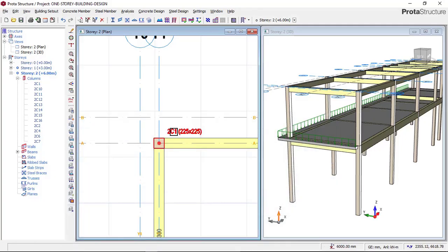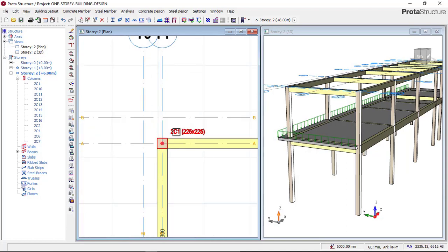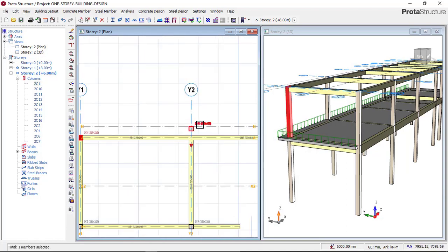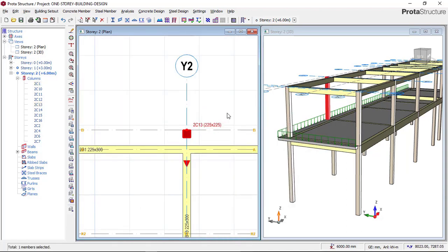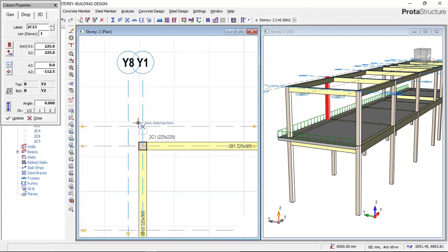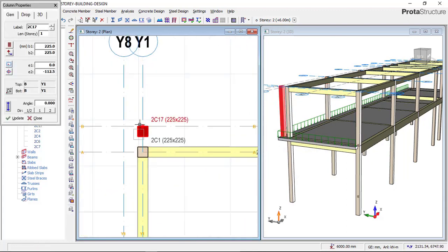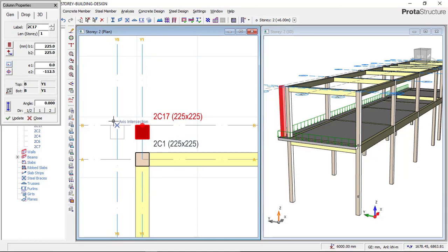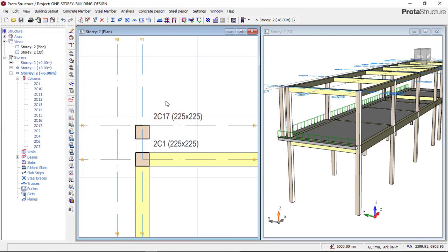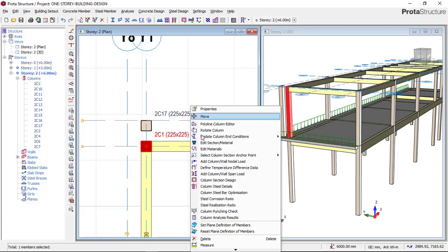So we go here, click at this place. Sorry, click on this. Let us take this column and click on the properties, come here and insert this column here. You can choose to put the column here or put the column at this edge here. So I choose to put the column here, and then I'll just click on escape and then come here and delete this column.